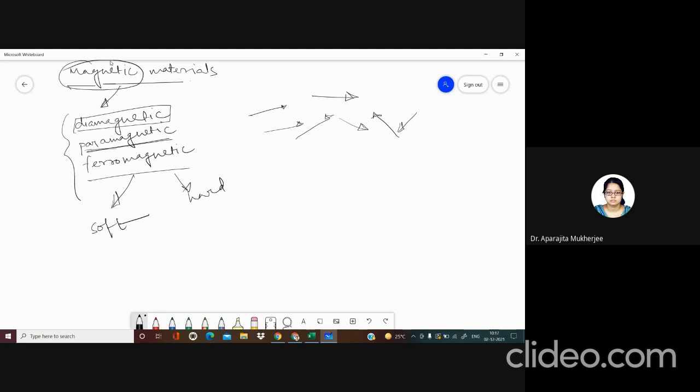Soft magnetic materials have high relative permeability, are easily magnetized and demagnetized, and have extremely small hysteresis. What are examples of these? They are mainly iron and its alloys with nickel, cobalt, tungsten, aluminium. Easy magnetization and demagnetization makes them highly suitable for applications involving changing magnetic flux, as in electromagnets, electric motors, generators, transformers, inductors, telephone receivers, relays. They are also useful for magnetic screening, and their properties may be greatly enhanced through careful manufacture.